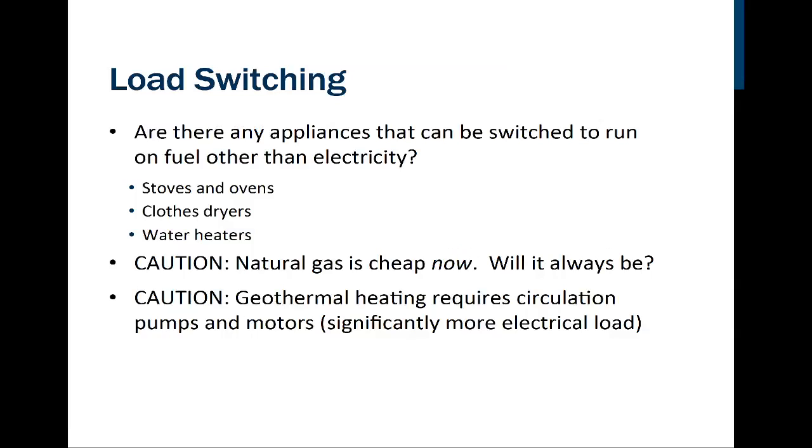The geothermal heating is kind of a misnomer. It's really a ground source heat pump here in this part of the country. So the ground source heat pump requires a lot of circulation and a lot of motors, which is a huge electrical load. So yes, you will be burning less gas, but your electricity bill will most certainly increase in proportion to the decreasing of the gas bill. And if you're not using geothermal, if you're just using an air-to-air heat pump, you will find that your electric bill goes up even higher.